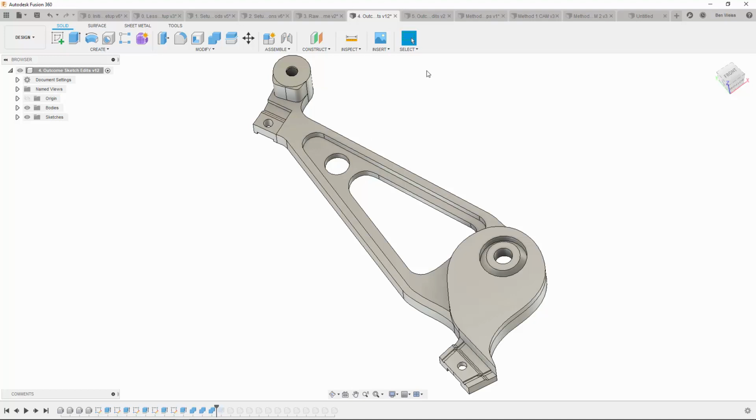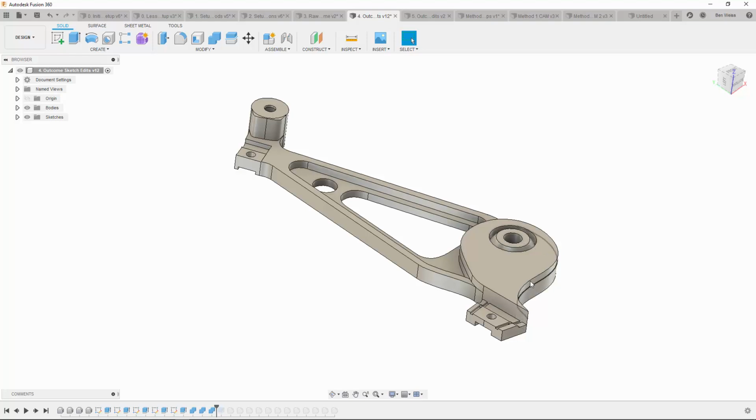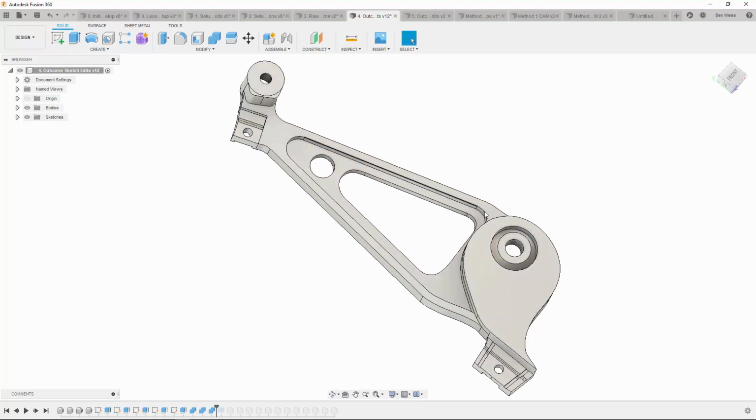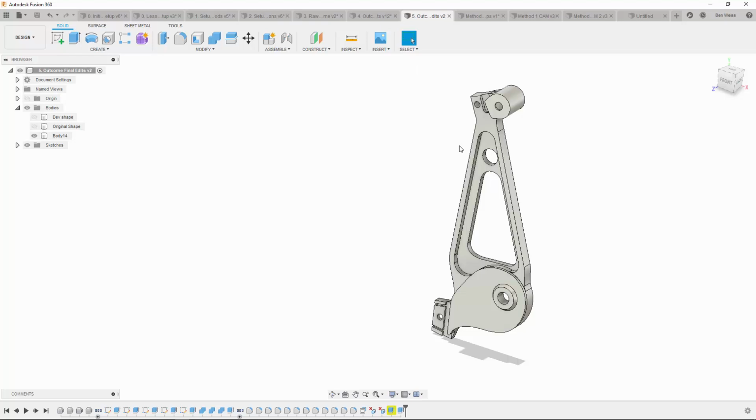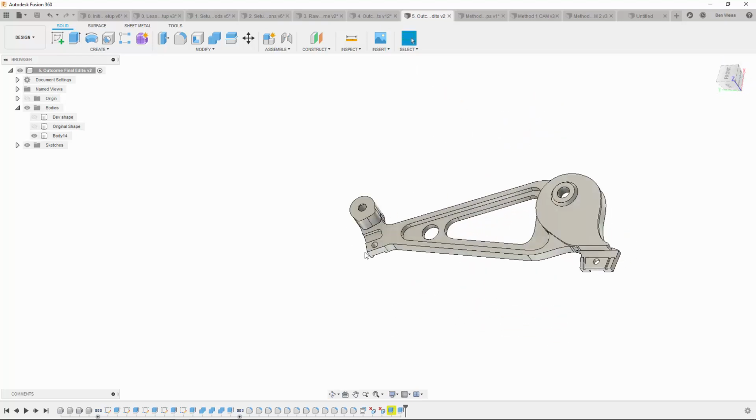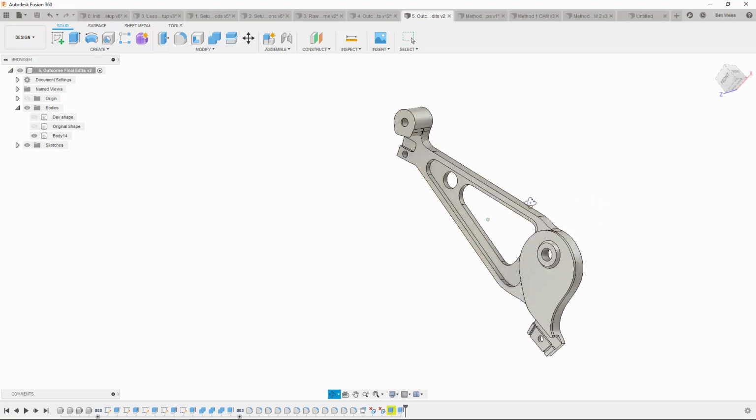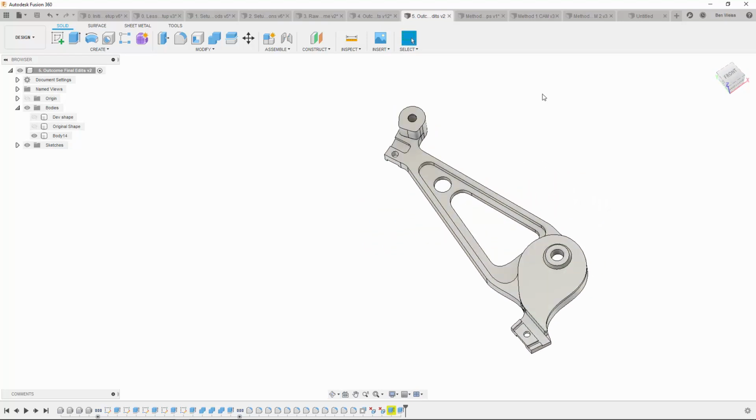There's still a few tweaks to do, a few touch-ups, which are the same touch-ups that you do anytime you're getting ready to run a model through CAM. We'll go around this profile and fillet any sharp corners that we find, check the radius. And we also did a design iteration at this point in the process where we discovered that the preserved geometries we've made weren't as manufacturable as we thought, so we went back through and tweaked them and didn't regenerate the solve. We just made modifications to the preserves by adding features to the timeline. So this one is now all ready for CAM.